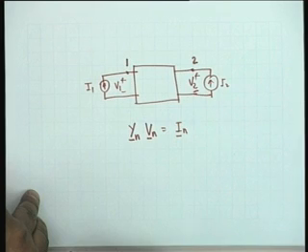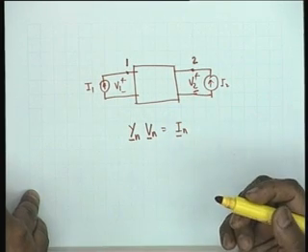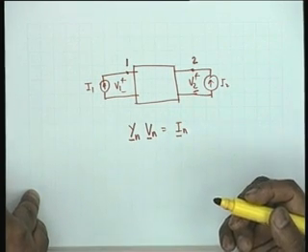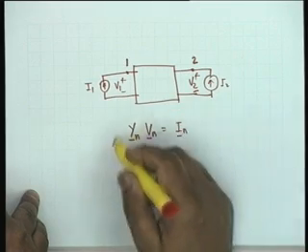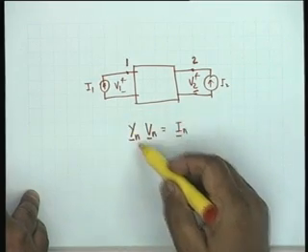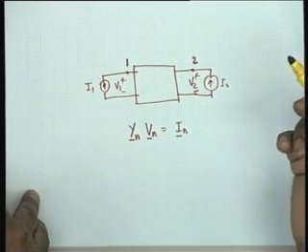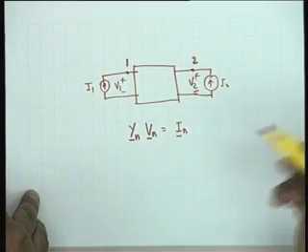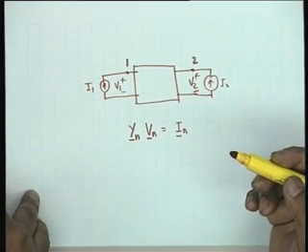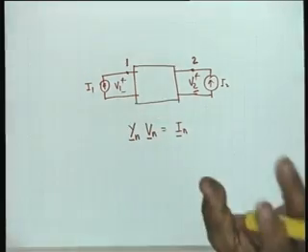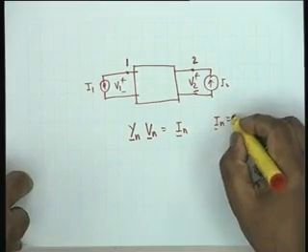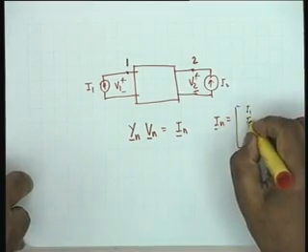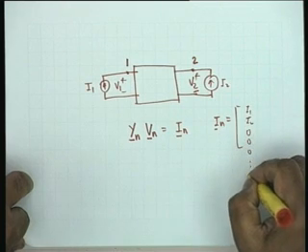This is the nodal analysis equation. It can be put in this matrix form. You have self admittances and mutual admittances and so on. Where I have just two generators, I1 and I2, so In is equal to I1, I2, then 0, 0, 0, etc.